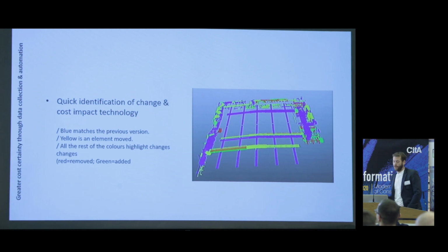From a QS perspective, when you add a new element to the model, it creates another level of work for us in linking and mapping our models to our cost breakdown structures and our bills of quantities. In order for this 5D to really work properly for automated updates, we first need to sit down and agree what we are going to call building elements or building parts within our model, so that the QS, the design team and the modeler are fully connected. This will speed up our process of change control, cost accuracy, our cost estimation, and so on.